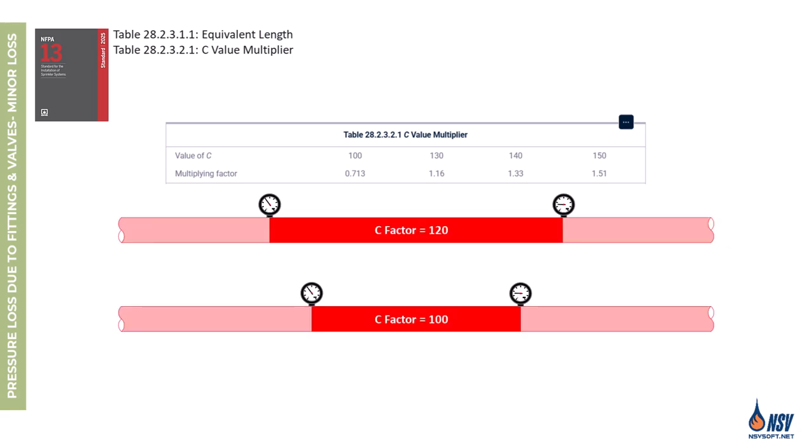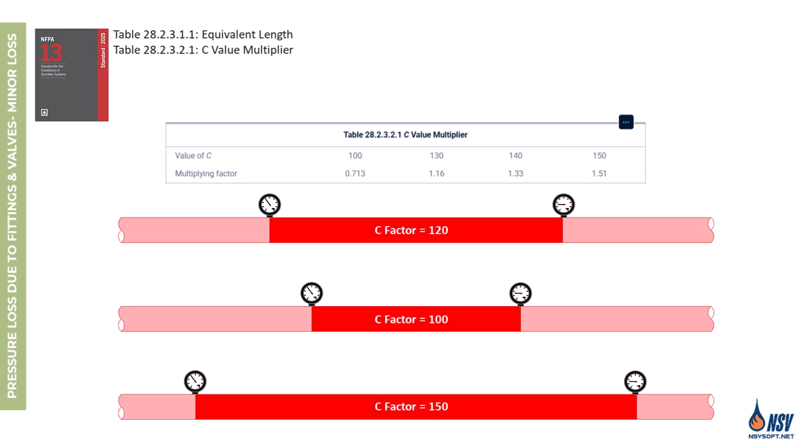In other words, rougher pipes create more friction, so the same amount of pressure loss occurs over a shorter length. When adjusting for smoother pipes, we need to extend that length to match the same pressure loss, which is why the correction factor becomes larger.